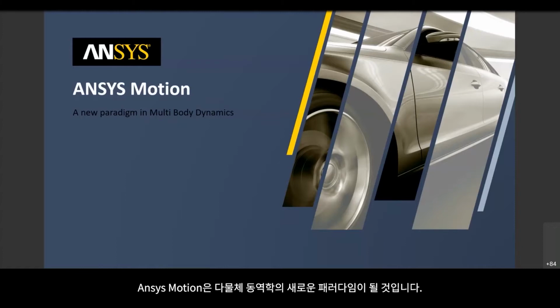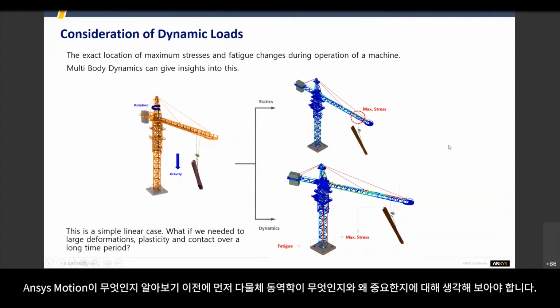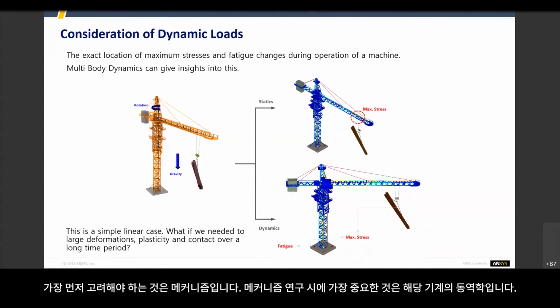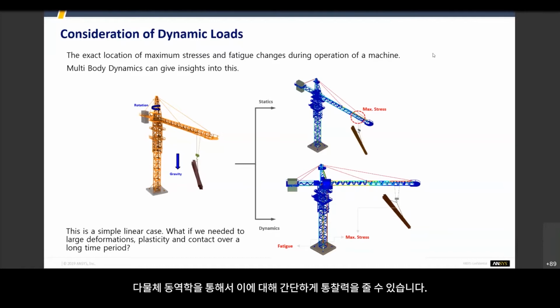So Ansys Motion is what we're calling a new paradigm in multi-body dynamics. Before we dive into what that means, we really need to think about what multi-body dynamics is and why that's important to us. When we think about multi-body dynamics, what we really need to be thinking about is mechanisms, the study of mechanisms. And whenever we study a mechanism, the kinematics of that mechanism are going to be important. They're important because when a mechanism is moving, the locations of maximum stress and the locations where fatigue might occur change due to the movement of that machine. And multi-body dynamics at a very simple level can give us insight into this.